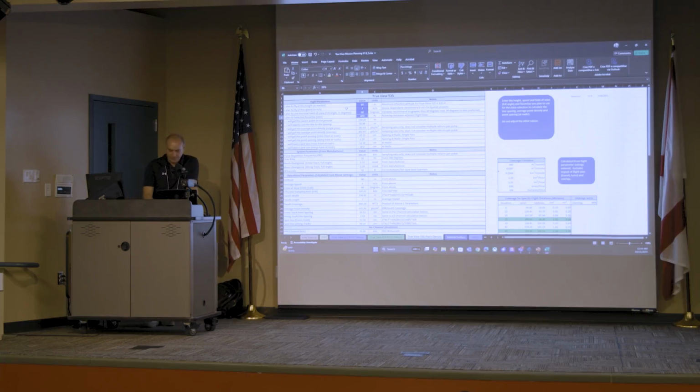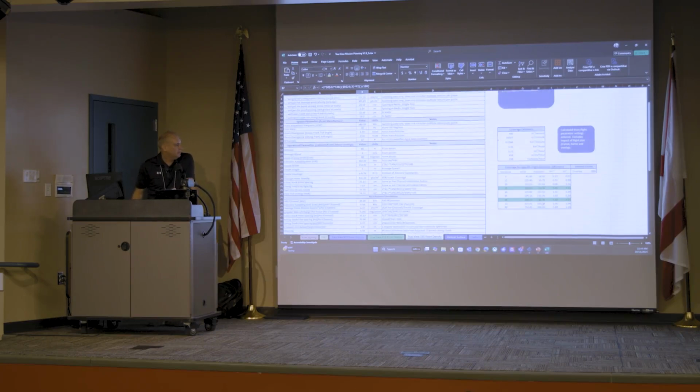For the overlap position, I would use like 40. And here, if you go on the right side, of course, you can also see the density of data, so how many points per square meter you're going to have using these settings. If you are doing a cross-flight, you can see that we're going to have double the numbers here. Or if I'm flying with 50% here, that means we are going to duplicate the amount of points that I have in the data set. But for them, the most important part as well is this side here.